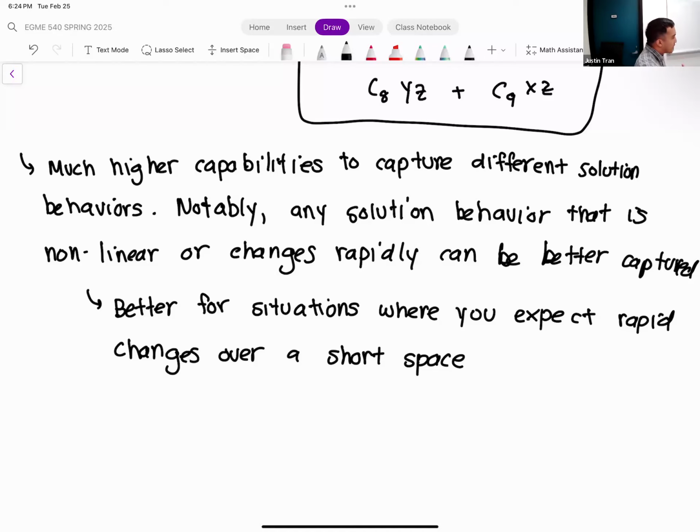If you notice in the last couple of activities, there's one part where I asked you to make predictions, which we skip in the lecture just because I forget about it. But I do that on purpose, so that when you run these simulations, you should have some expectation, some prediction of what you expect the results to look like. That's going to inform where you should put the elements and how you should arrange the mesh density. So that's a very important step that I skip in the lecture, so make sure you're really thinking about that, especially for your midterm project.